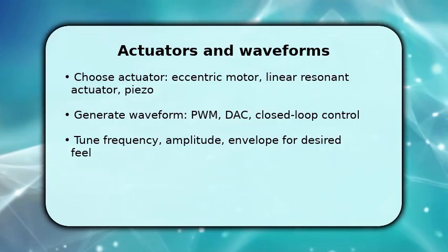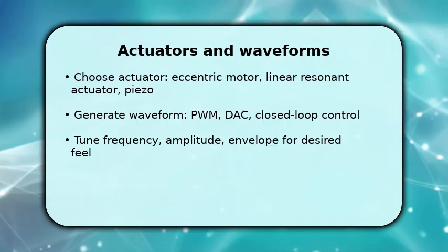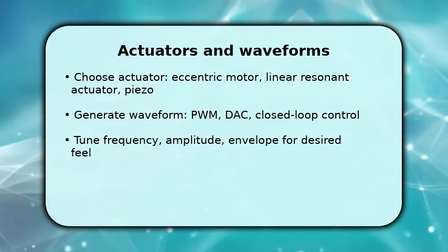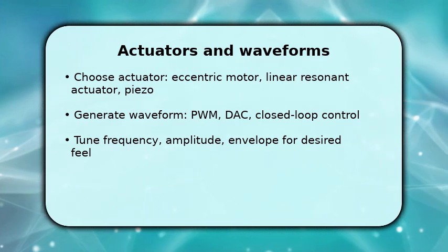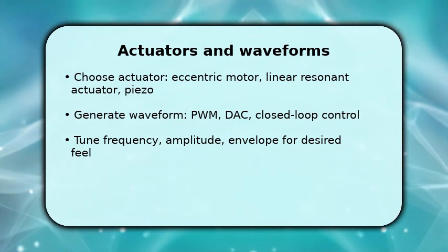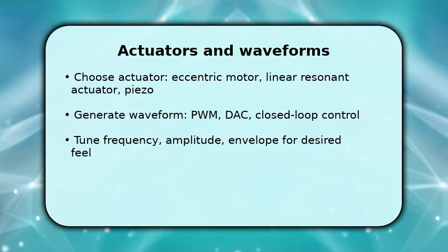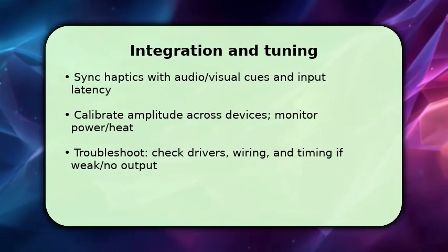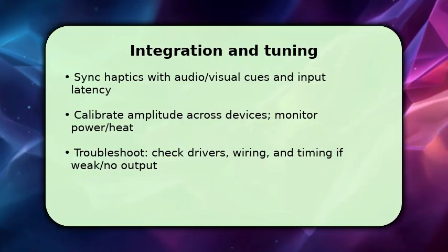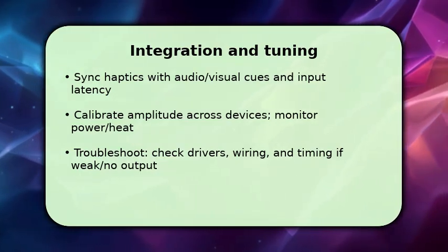Once driven, frequency and amplitude determine perceived strength and texture, while the envelope shapes onset and decay. Make sure to balance power and thermal limits as you implement the waveform. You finalize by integrating haptics into the system. Synchronize vibrations with sound and visuals, and account for input latency so sensations feel immediate.